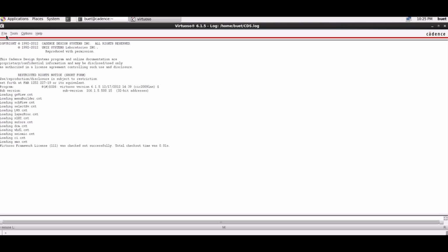This design employs components from the Cadence design kit libraries, which we will be creating right now. It is recommended that you use a library to store related cell views. For example, use a library to hold all the cell views for a single project. In our example, we are going to create a new library for our design and attach it to the desired